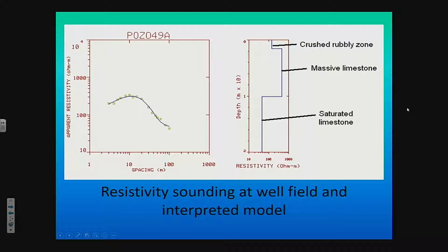You can see the resistivity drops significantly when you hit the water table. So you're doing all this on the surface, there's no wells involved. But the system senses when the resistivity goes up and when it goes down. So it's kind of neat, it actually works. And you can see below the surface with it by just doing surface measurements.